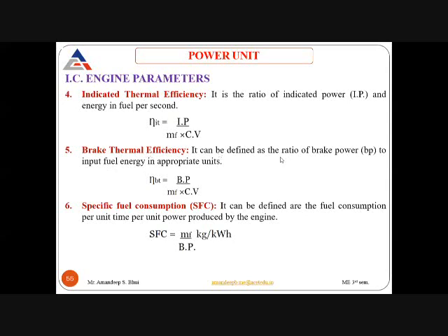Next is brake thermal efficiency. Brake thermal efficiency is the ratio of brake power to the energy that is available with the fuel. So brake thermal efficiency is brake power divided by the energy with the fuel, which is mass flow rate multiplied by the calorific value of the fuel.